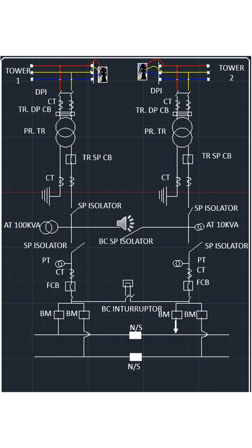For energizing the transformer, first you must close the no load switch, meaning the isolator switch. Isolator switches close in air. So if you close it in live condition, then a spark over will take place and the isolator will be melted. Why?